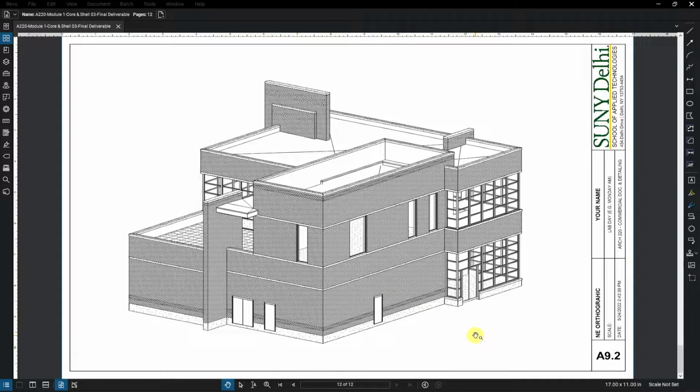Some standard profiles for wall sweeps are included in the Revit architectural template, like sweeps that are exactly one brick in height, which we will be using. For other more distinct sweeps, such as our cast stone water table windowsill, we are going to be making our own profiles, which are essentially loadable families. So we're going to be delving into creating our own custom families in this assignment.